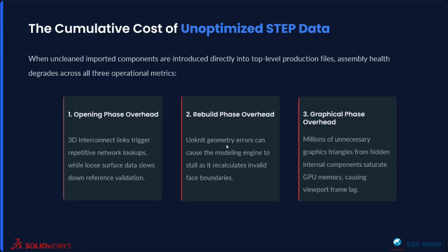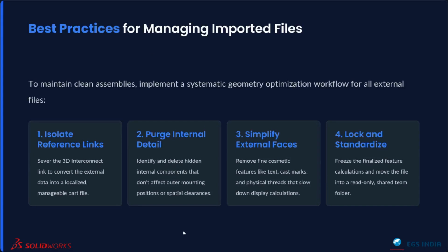So how are we going to solve it? I have a simple 4 to 5 step process for managing these imported files. The first one is to isolate your components. Instead of maintaining the link with your existing step file or neutral files, we are going to cut the link and save it as a separate part file.